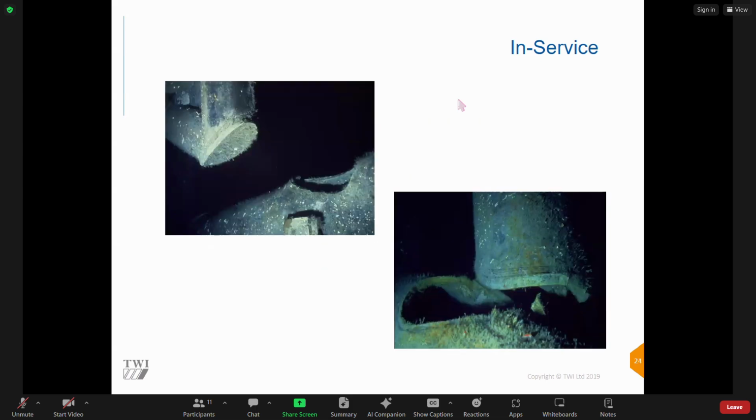Well, there's a good example of a fatigue failure. Okay. So again, it also shows residual stress as well. Okay, because we can see how far the two components have moved away from each other. So they were perhaps force fitted, welded up.